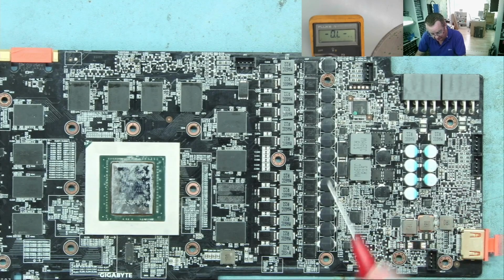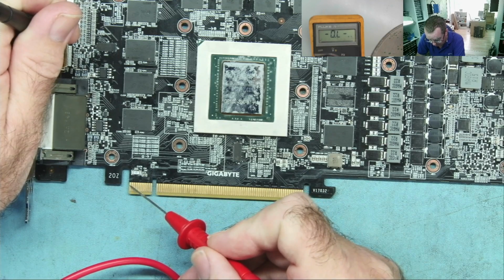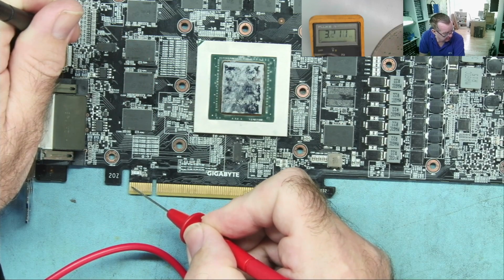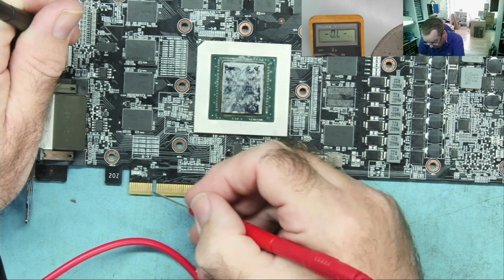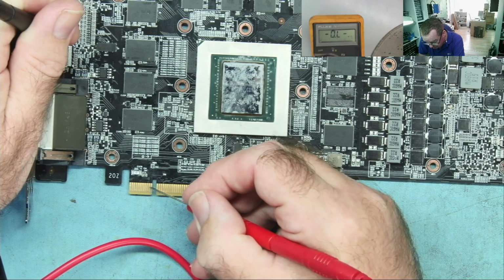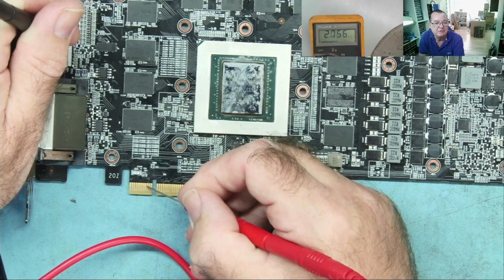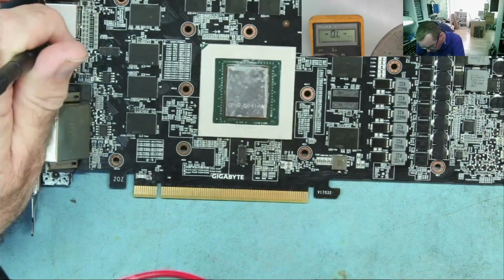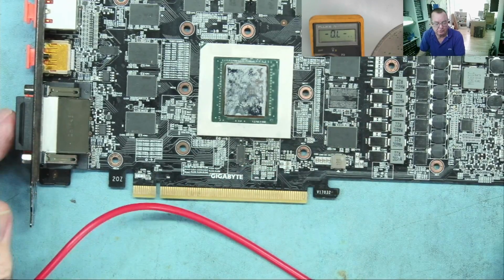Well, let's do the same methodical method. So first of all, the first 3 pins is 12 volts. And that reads in the kilo ohms, so there's no short there, okay? Fourth one in for me is a 3.3, 1, 2, 3, pin 4. Again, it reads 32 kilo ohms, it's in the kilo ohms, there's no short there. Is there any fuses down here? This looks like it might be a fuse. And it reads short as you expect.